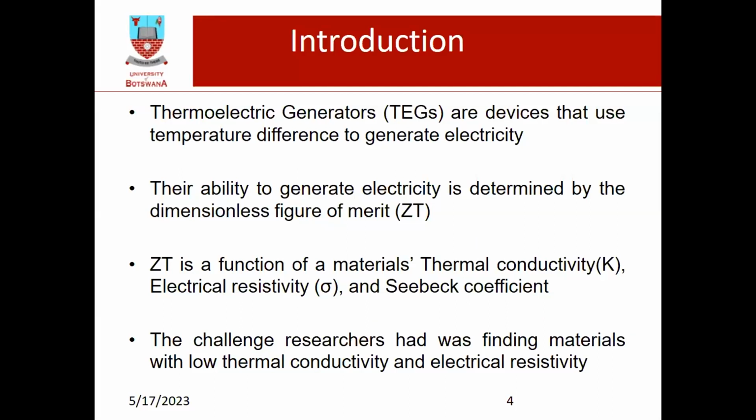So, the basics of what we are talking about: what are thermoelectric generators? These are devices that use a temperature difference, requiring a hot side and a cold side, to generate electricity. Their ability to do this is governed by a dimensionless figure of merit, ZT, which is a function of the thermoelement materials' thermal conductivity, electrical resistivity, and the Seebeck coefficient.